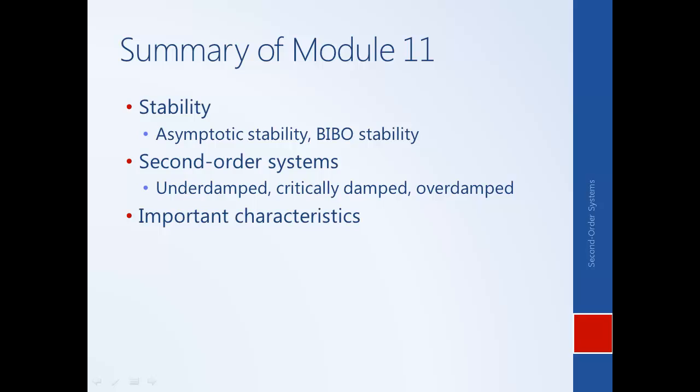And then we looked at the second-order step response, in particular the properties of settling time, peak time, and maximum overshoot, and we related the parameters of the step response to the parameters of the second-order canonical system, zeta, omega n, etc.